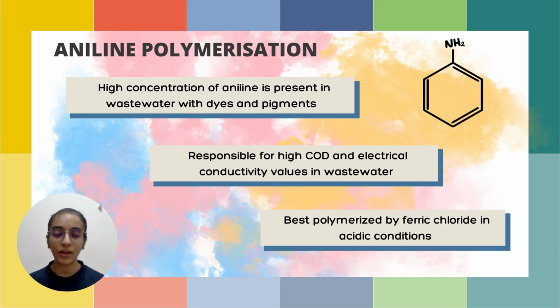This is because the aniline polymers themselves are electrically conductive, and hence a higher value of electrical conductivity in a wastewater will denote their presence. To treat this, aniline is best polymerized by ferric chloride in acidic conditions.